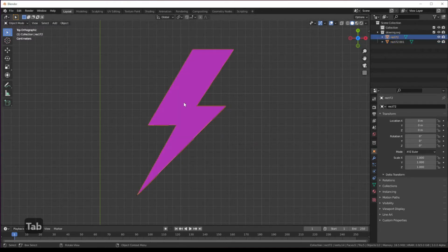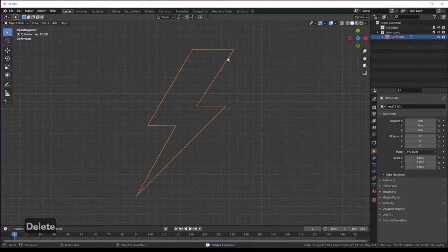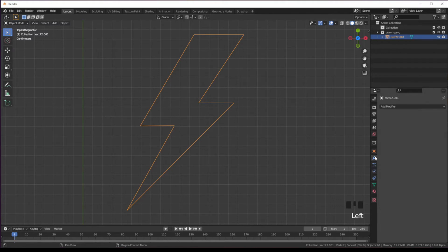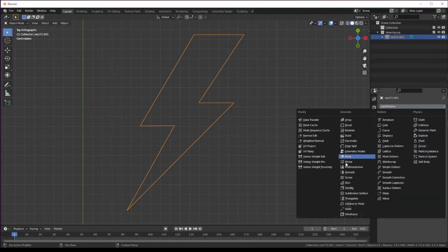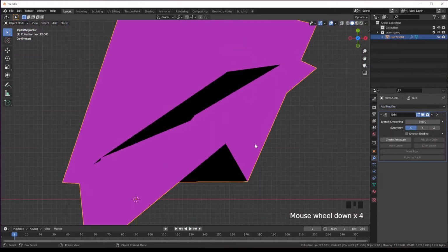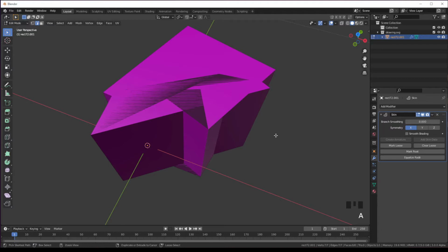I'm going to make a neon-like light, so with the border mesh selected in Object Mode, go to the Modifiers tab and select the Skin modifier. Now I know guys, this is a mess, so go to Edit Mode, select all and resize the modifier impact with Ctrl A.